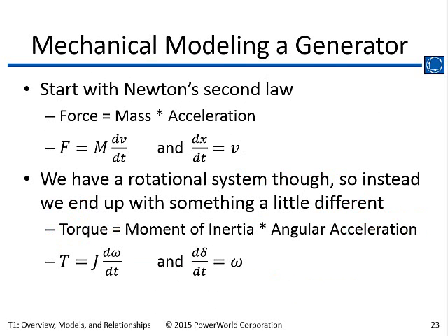Most people are familiar with the swing equation because it's covered in an undergrad class. But the gist of it is that when you've got a spinning rotor and you're looking at it in kind of a steady state representation, as though we're strobing that rotor, which would really be spinning at 3,600 RPM or 1,800 RPM, when you strobe it at the synchronous frequency, you can think of the torque angle on that generator as being constant as long as the mechanical power into the generator matches the electrical power out of the generator. When those two get out of whack, then you get dynamics going on, and a primary way for them to get out of whack is as a result of a fault.